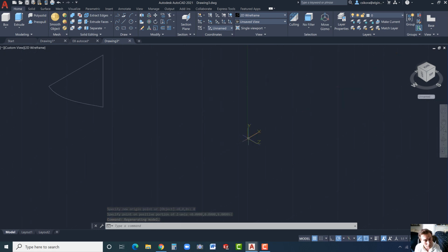I'm just using my mouse. Notice I point the mouse where I want to zoom up to while I scroll the wheel. Okay, and I know you can't see that on my pointer. So, okay, now we're going to set the grid back on. We have the line tool selected. Click on this. We'll make this, get it to the left. We'll make it 0.7. Enter. Hit escape. And now enter again, click on that point, and down 0.6, enter, and hit escape.